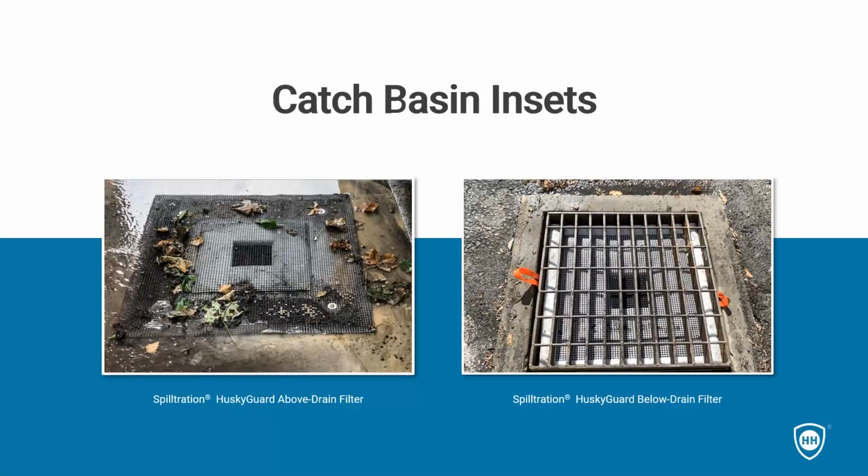Catch basin inserts. This is something that we are seeing used a lot more, both for companies, facilities, and also at the municipality level, also for any kind of commercial operations. And catch basin inserts are just a way to help you at that final point before something leaves your facility. If you don't have a retention pond, if you don't have any kind of an underground storage vault or something where your water from a paved area is going before it leaves your facility, catch basin inserts are just that last ditch effort to capture something before it might leave and get into a waterway.